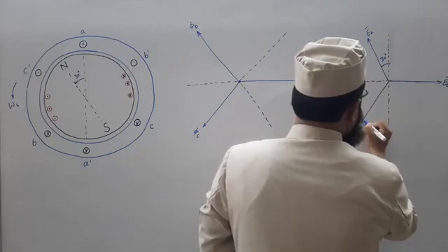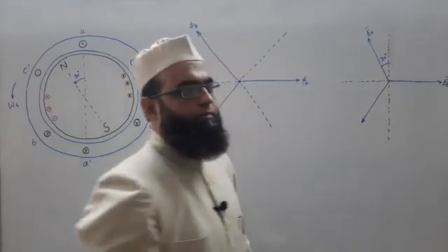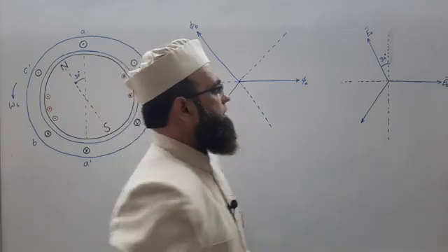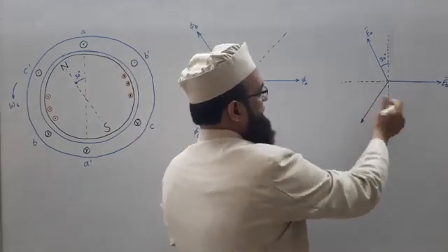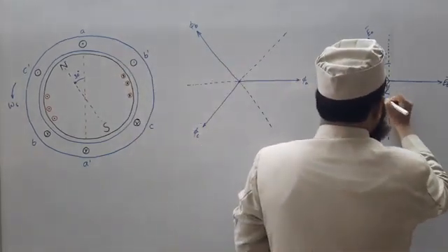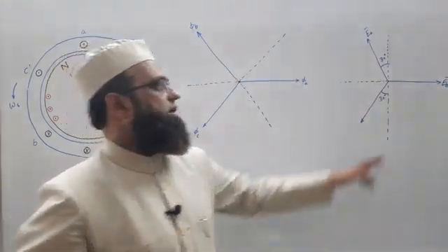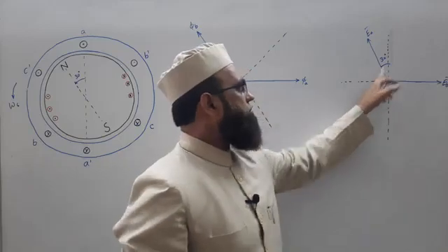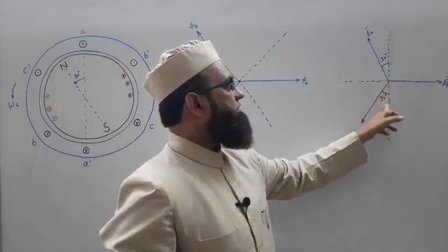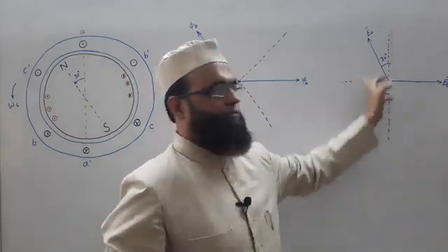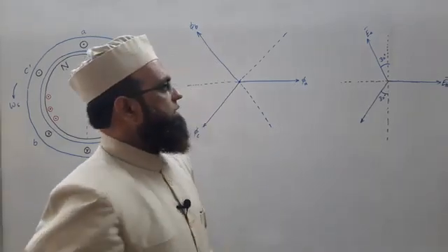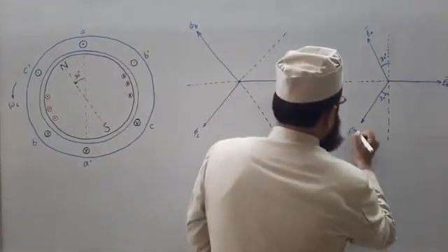All three phasors are rotated by 30 degrees. So, earlier it was making an angle of 60 degrees, now it will make an angle of 30 degrees with the vertical axis. So, 90 plus 30, 120, or here you can check 30 plus 30, 60, plus 120, 180, right. Write it EC.